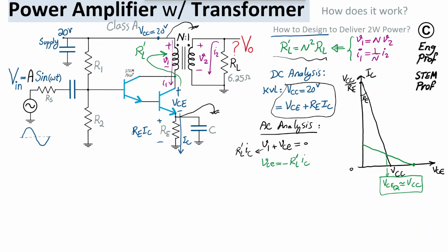And then for the quiescent point or the bias point of the transistor, we also have this value, ICQ, the collector current at the DC or bias point, the quiescent current, and then this node naturally becomes 2 times ICQ. For the proper design, we are trying to maximize the use case of transistors. So basically there is a DC current ICQ passing through the transistor via proper bias.